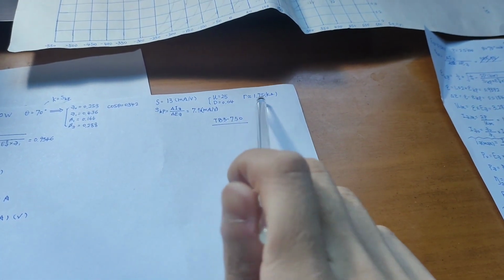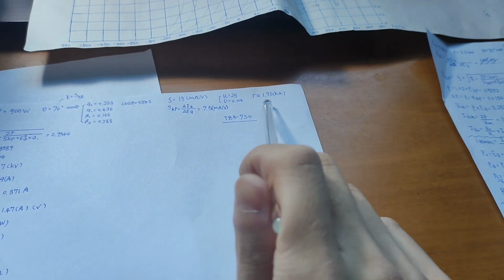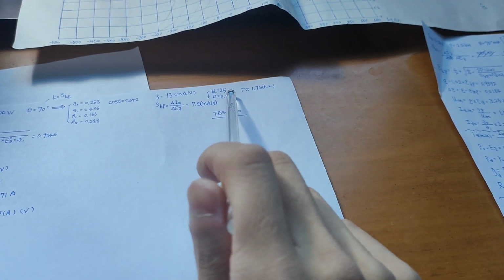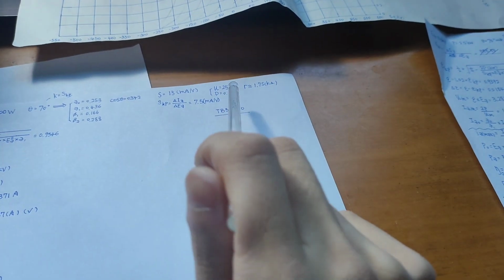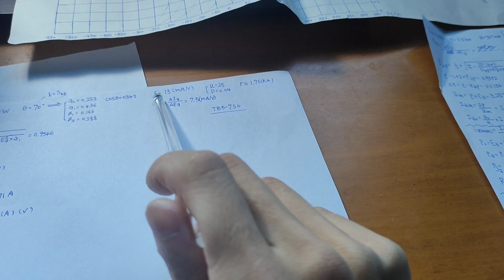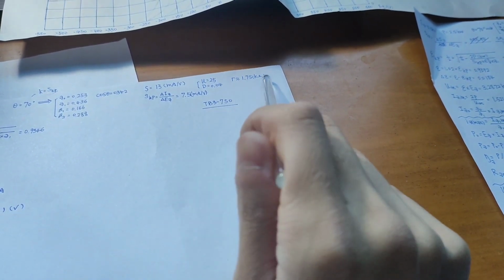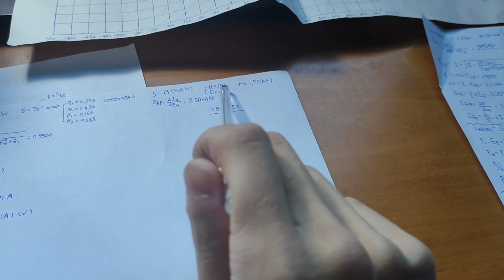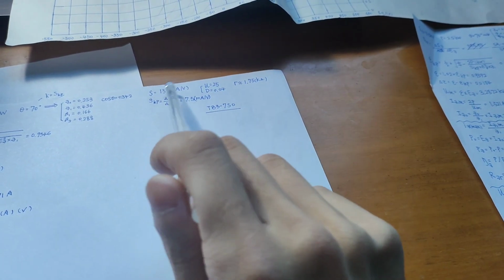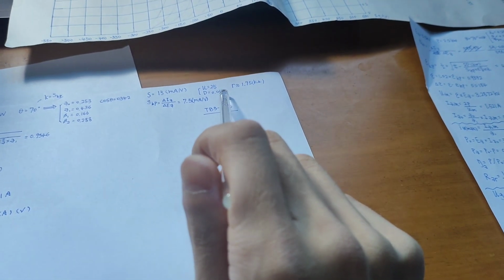And the internal resistance is just here. We don't need to use this one, but among vacuum tubes, a very famous equation says that the transconductance times the internal resistance equals the amplification factor. So if you know two of the three numbers, you can calculate the last one.